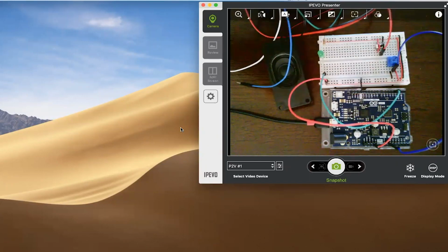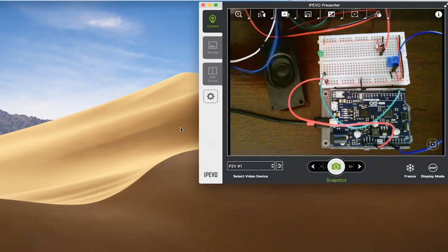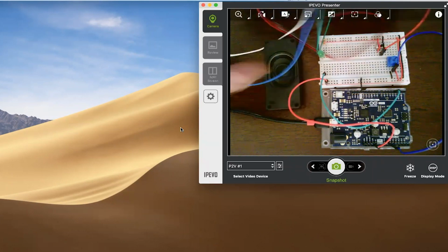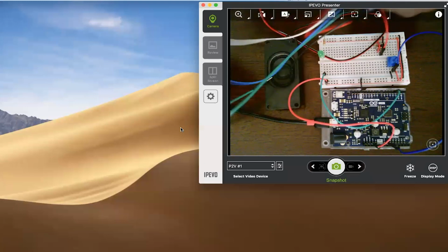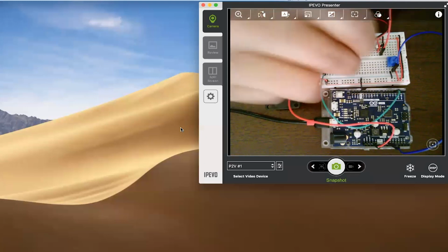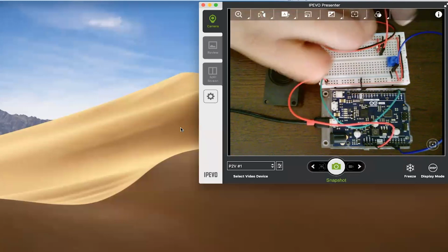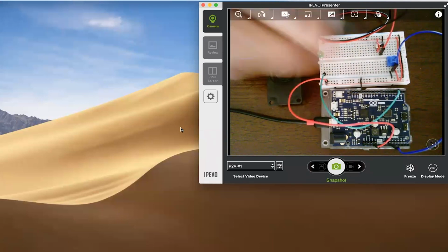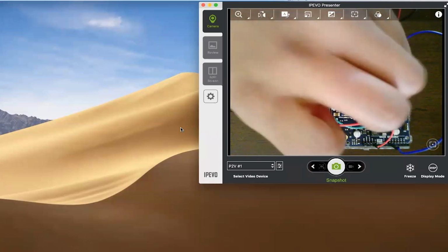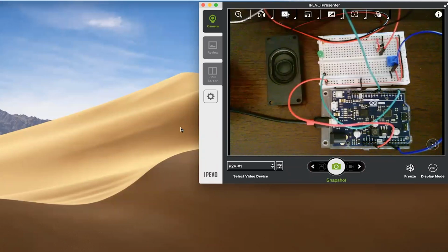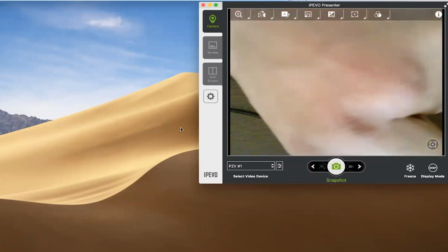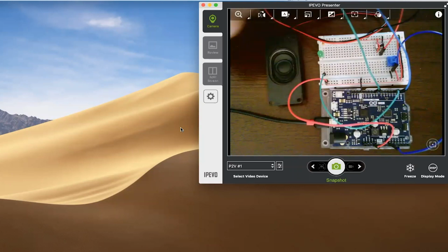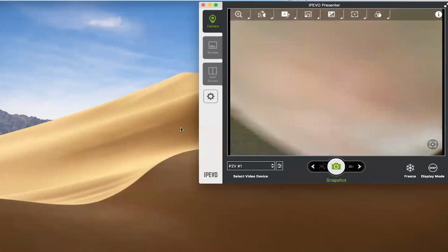I have a switch there which I can turn on and off. The next wire, let me bring it in the shot, is the ground wire. The next one over here is the data line, which I connected to pin 9. One is the clock line, which I connect to pin 0. And finally, this one.